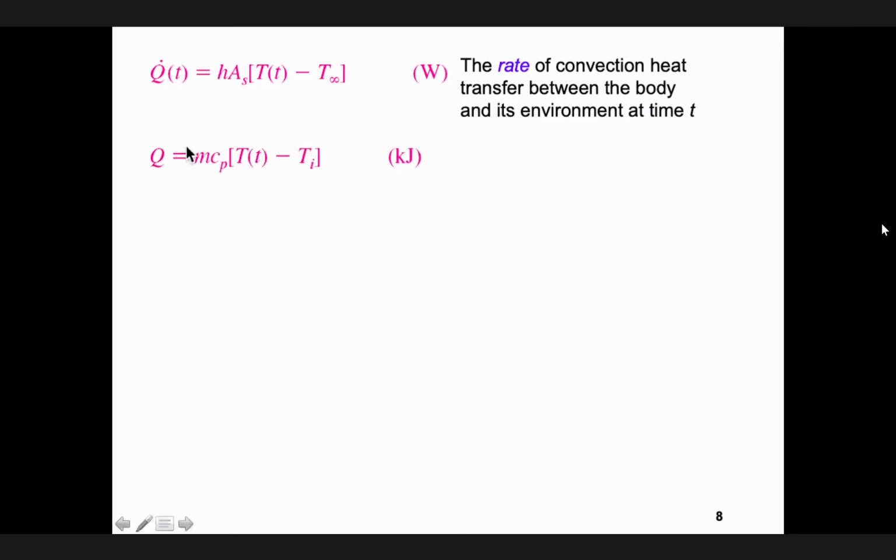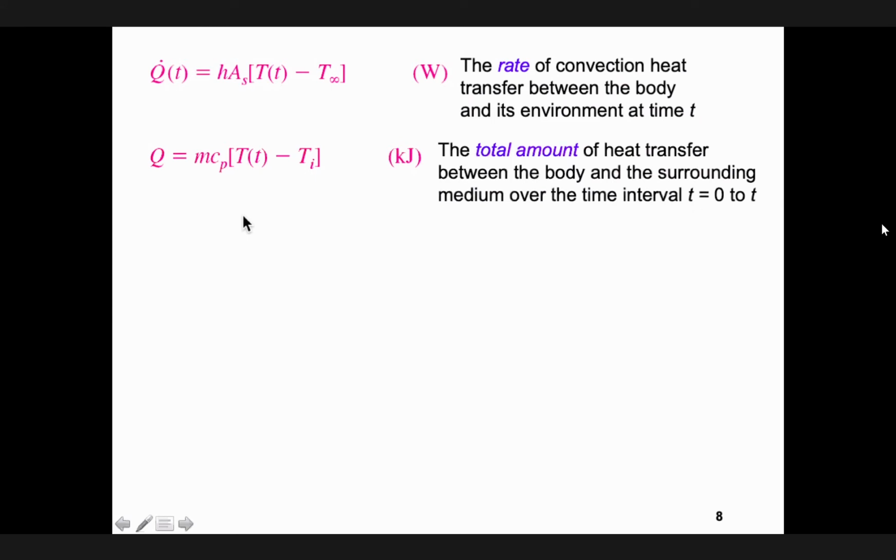And also you can calculate how much energy is lost from the system, because when you calculate T, you can put it in this equation and say, okay, this is the amount of energy that at this moment exists in the system, because the temperature was 37, now dropped to 35. Therefore, this is the remaining energy in the system, okay? Therefore, these are the expressions. Now you can see the temperature is changing as a function of time. It's not a steady state anymore. It's changing as a function of time, okay?